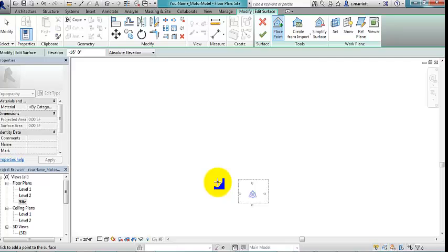little bit easier. So to start with, I'm going to articulate the contours of the flat contour of the site itself. My level 1 will be at 0 feet 0 inches, so I'm going to make that surface ever so slightly below that. So when you go into Topo Surface, you'll be given the option to place points.